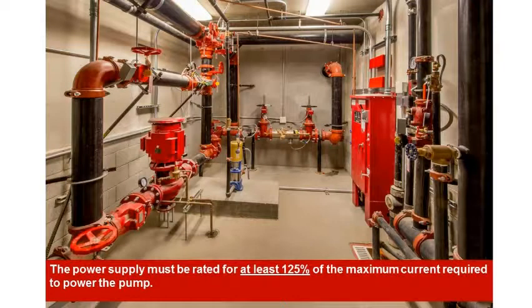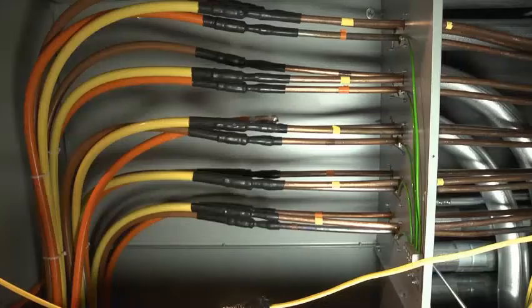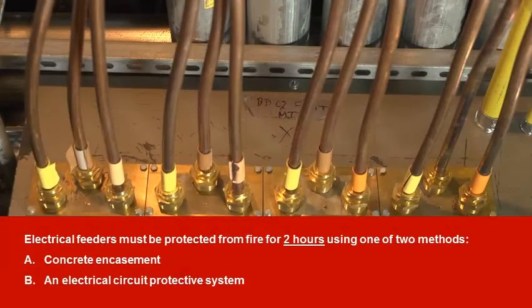What do these codes have to say about electrical feeders for fire pumps? First, the code says that the power supply must be rated for at least 125% of the maximum current required to power the pump. In addition, feeders must be protected from fire. Regarding feeders, fire pump supply conductors, where routed through a building, the conductor shall be protected from fire for 2 hours using one of the following methods.